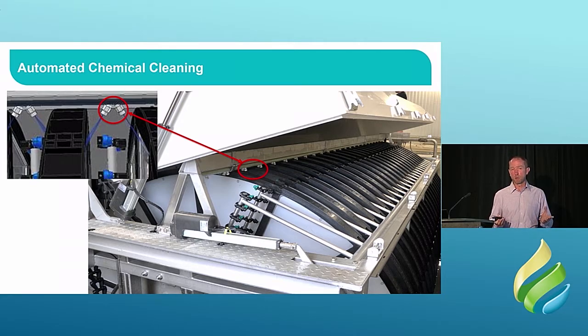I should say also, in tertiary wastewater filtration, you are going to need to chemically clean sooner or later. It's wastewater, things grow in there. So the most common need for cleaning is the bleach to get rid of organic growth. Some other reasons for doing it could be if you're using ferric, then you can get some iron type scales forming. If you're in a hard water area, you can get calcium and magnesium scales forming. But for sure, sooner or later, to maintain filtration performance, you will need to chemically clean. It varies from about every few weeks to every few months.